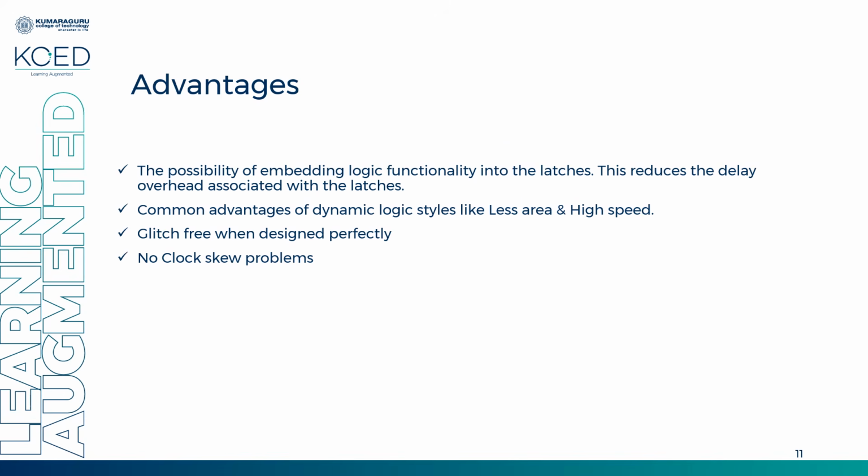So an advantage is that you can design both latch as well as logic. You can design latches and registers. Apart from that, you can embed logic into the TSPC pipeline structure. As you have seen before the D flip-flop, I showed you NMOS logic and PMOS logic, where you can embed your logic.